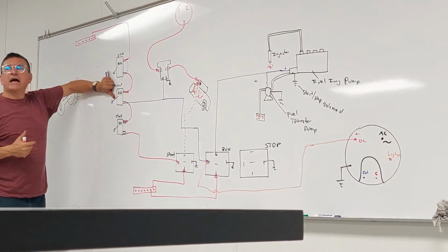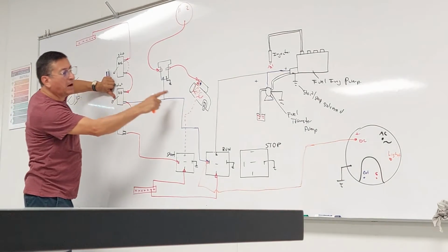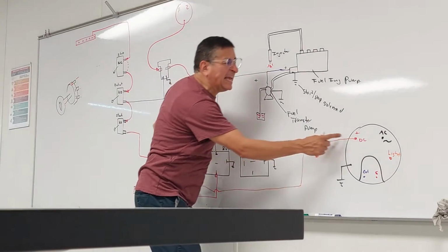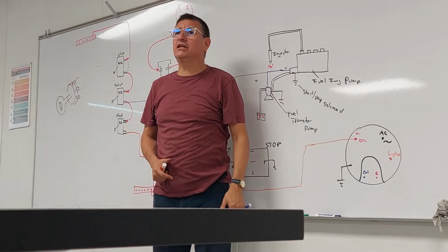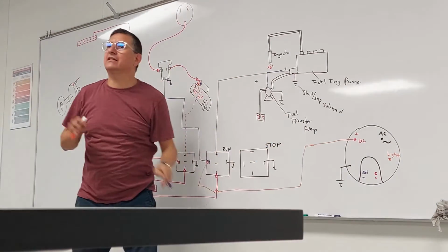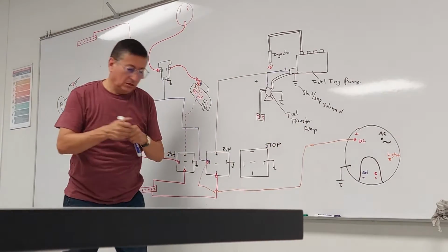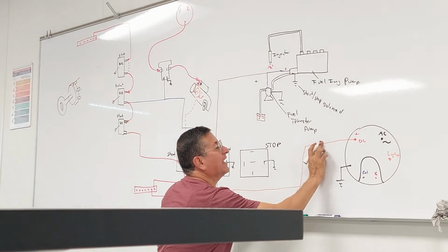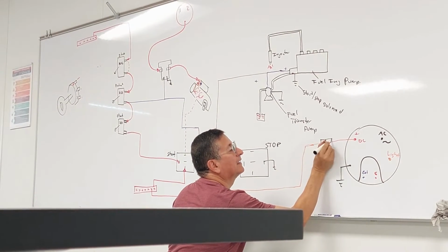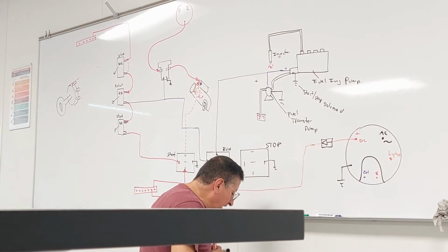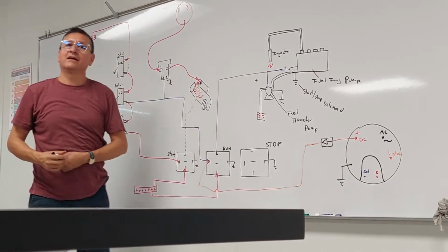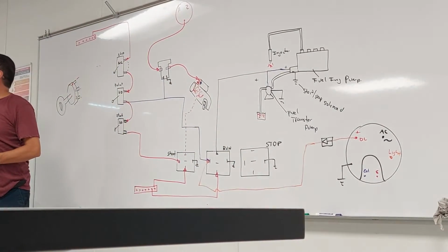During the preheat, when I press that one, I bring power here, and I bring power here in the output. Is that good? No. I damage the winding of the alternator. How can I protect the alternator from that issue? Correct. I install one diode here to protect it. This is the only diode that you have in the harness, to protect the alternator.